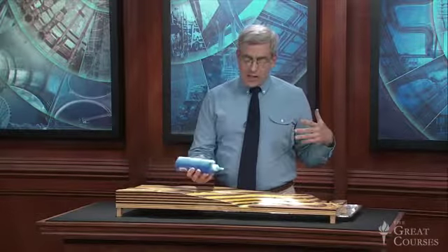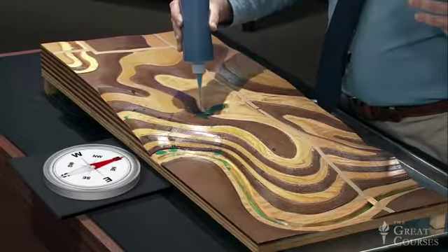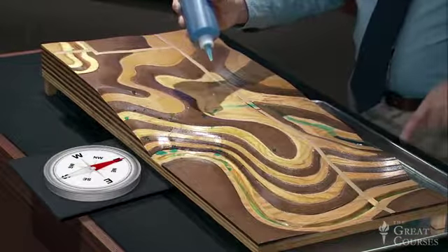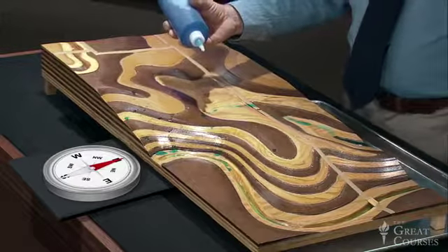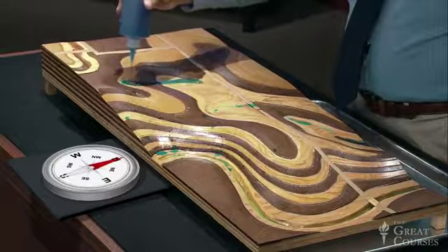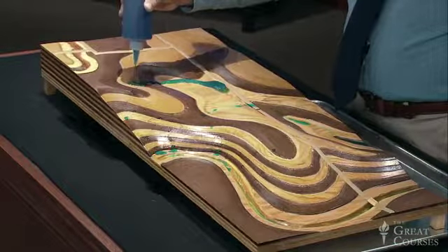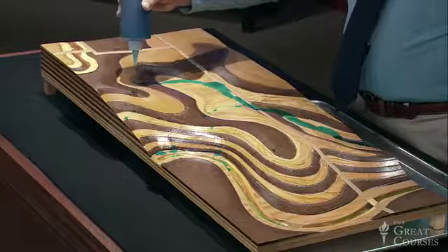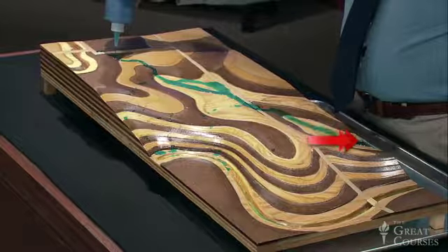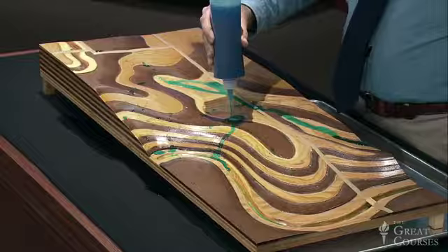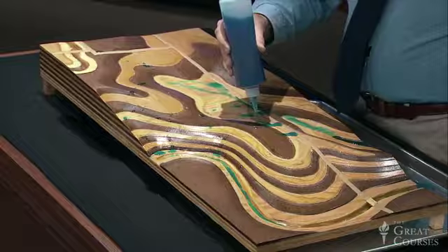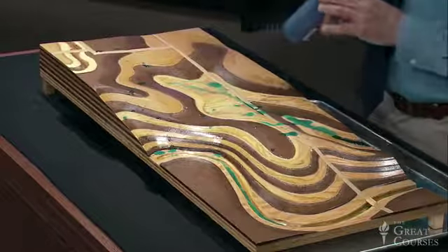And no matter where I deposit it, that water will eventually be collecting at the low area here, picked up by this draw and channeled down ultimately into the river valley, which extends beyond my map up here to the north. So once again, I'll deposit water here. It eventually follows that roadway down, crosses over at the low spot, and ultimately departs from our project site. And once again here, as long as I'm on the north side of the ridgeline, the water is ultimately going to end up in that same draw.